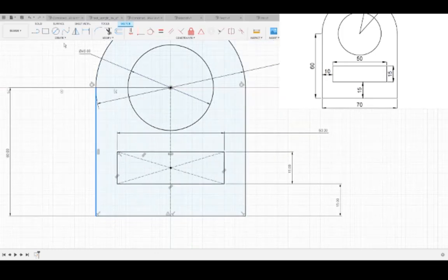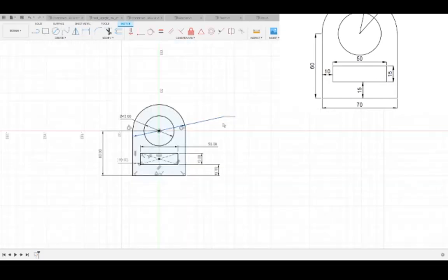Because if, let's say, I set the driven dimension, I'll make that 10 millimeters, it's set. See, if I were to change the radius of this to say 80 millimeters, this dimension changes because it's driven, whereas all these other dimensions that are non-driven are driving.